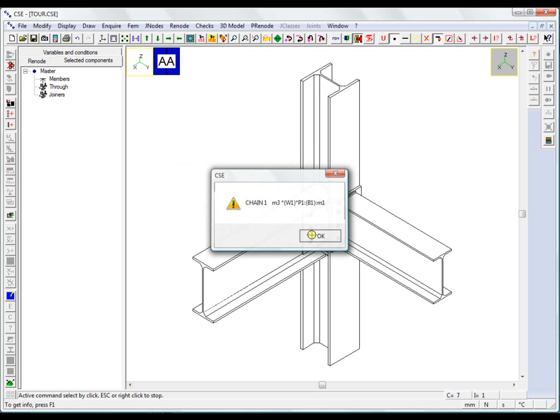Strength checks on the various bolts and welds, bearing stress checks on all the objects pierced by bolts, and the checks on the net sections of the members. For this connection, we have not checked the compression between the plate and the column flange, nor have the entities been checked using automatically created FEM models. For both these aspects, please see the previous video.